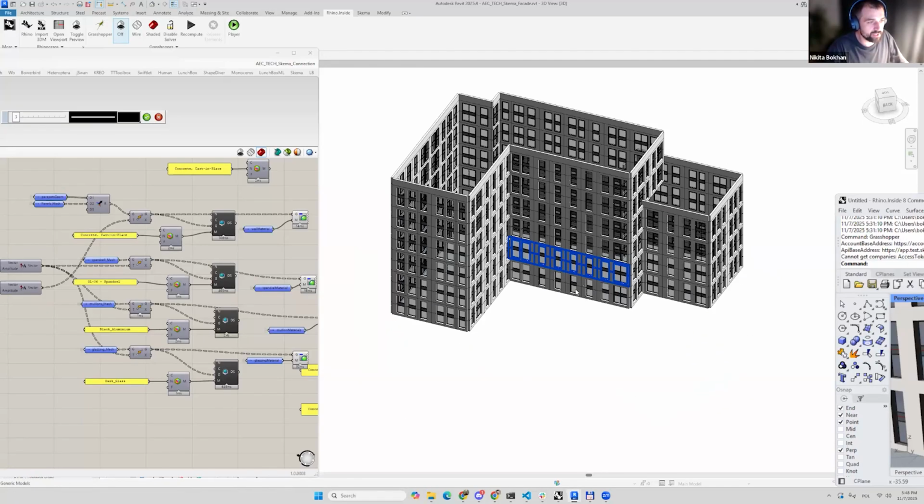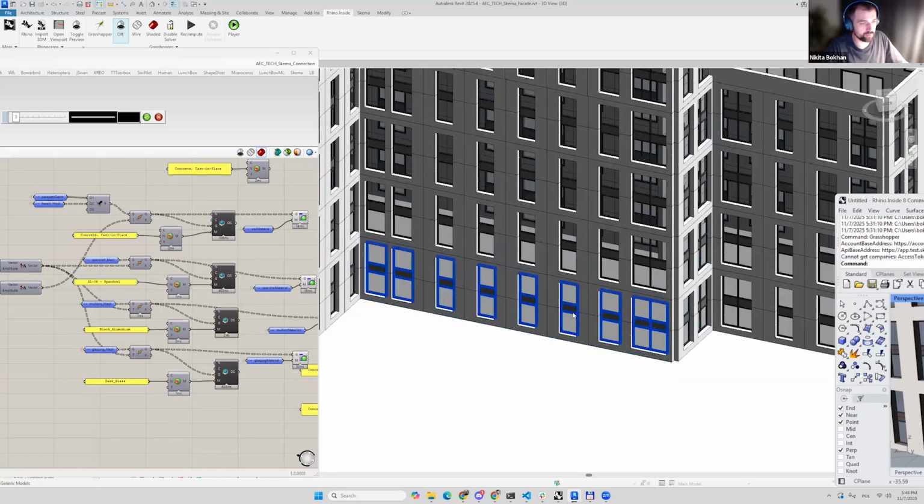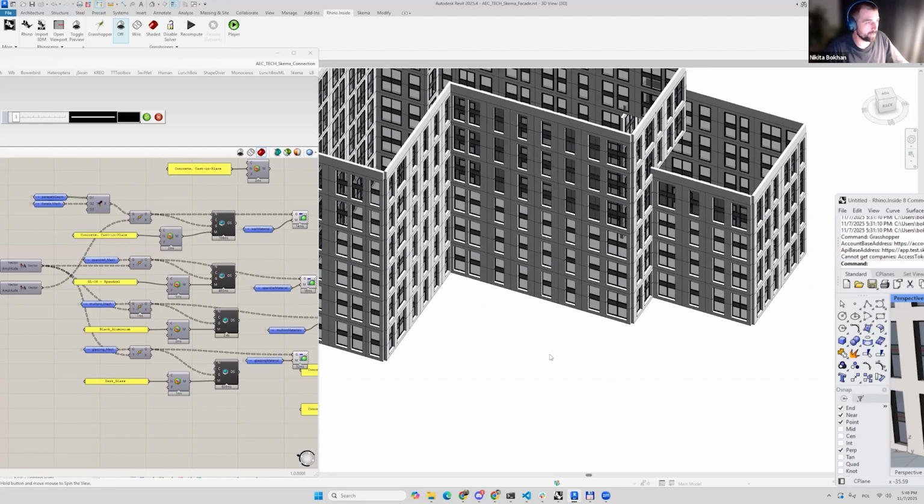I personally did some tests exporting everything as a curtain wall, a curtain wall embedded into another curtain wall, but doing it from Rhino.Inside is a complete mess and waste of time. Obviously, it makes no sense at all. So I came up with this approach: direct shapes work pretty well. We can treat direct shapes as walls, as categories, and everything will be okay in Revit. But we can also create walls instead of direct shapes.